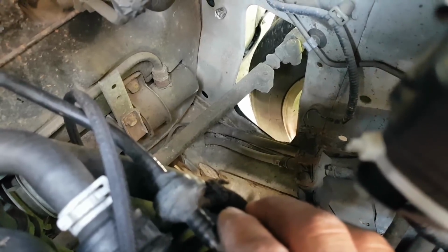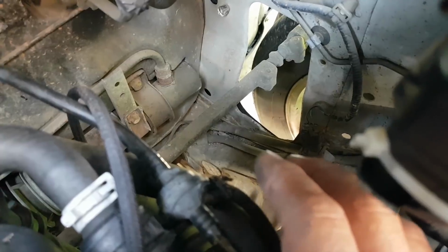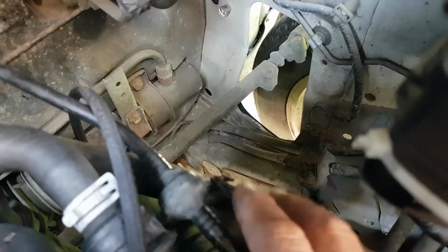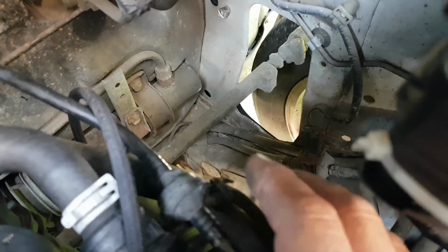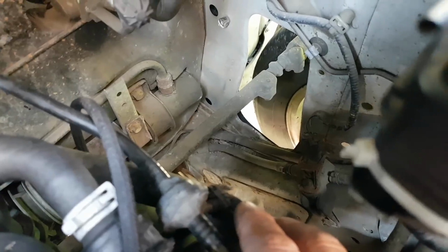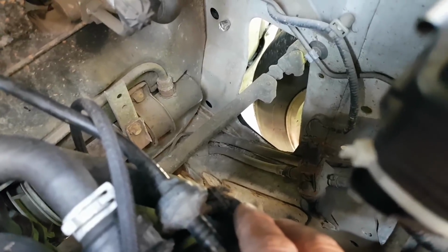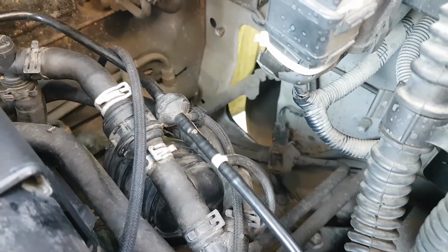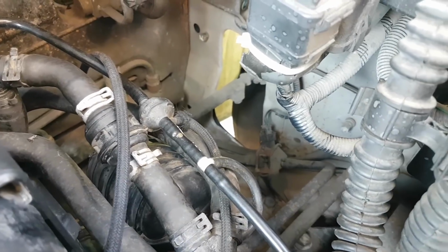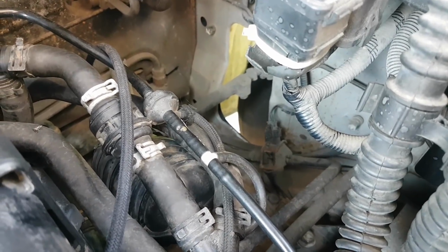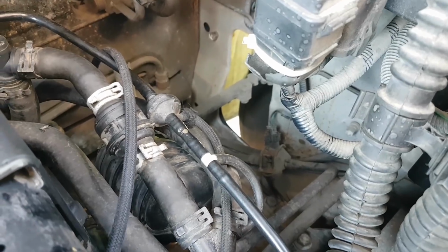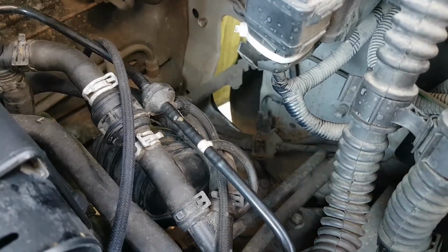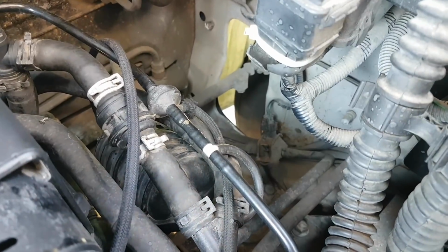I don't have a manual gauge for this, so I'm not going to be able to connect anything into these lines, which is a shame. So I'm going to have to investigate this a little bit further and try to find out something. I'm going to measure the sensor voltage and all that, and we'll go from there. But it's going to be fine now because the car is driving fine. So it's going to be one of the two things. I can't see anything else: either the sensor or the fuel pump in the tank.